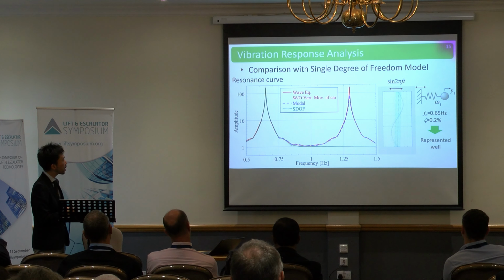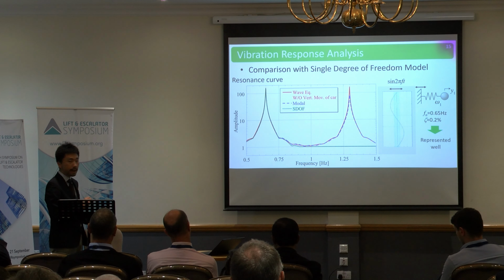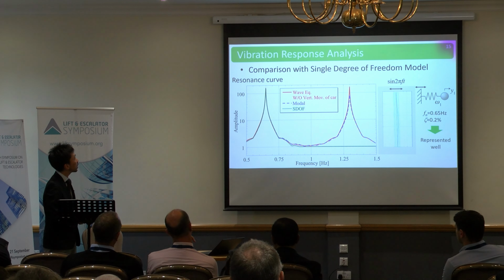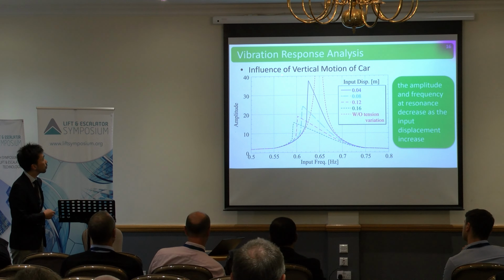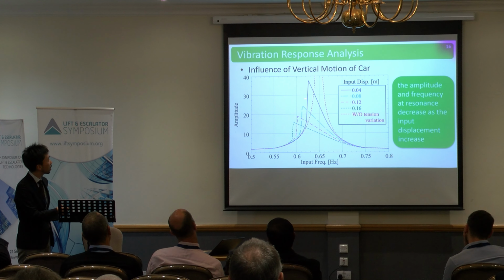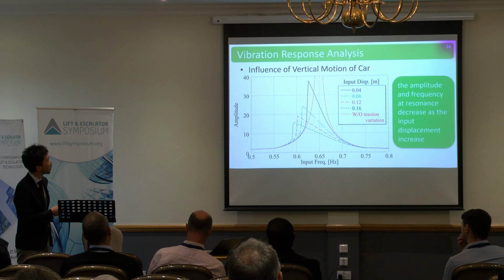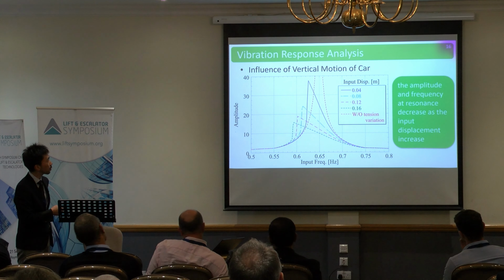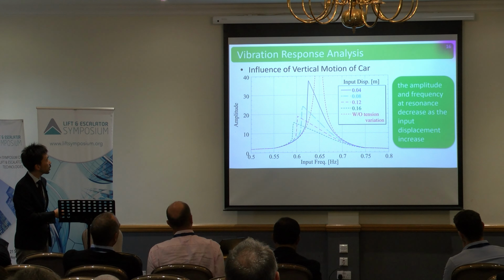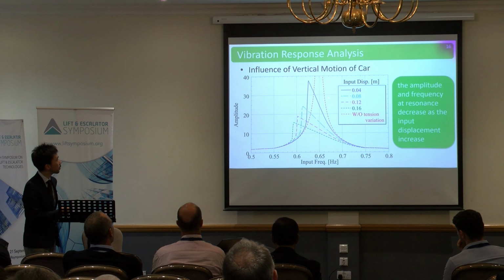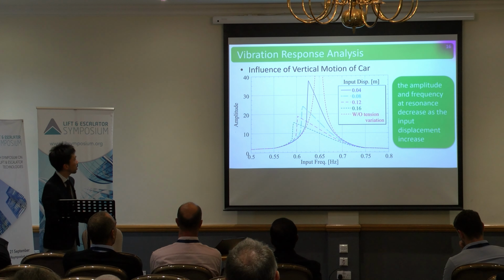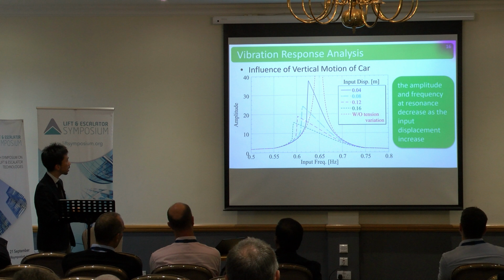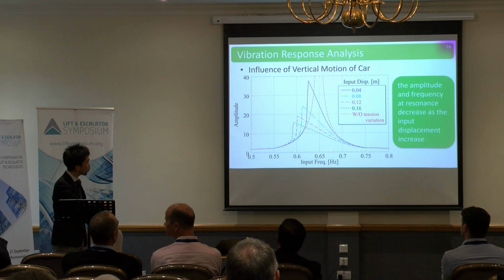So maybe we can use the single degree of freedom model and modal model for rough analysis of the vibration. However, if we consider the influence of vertical motion of the car, the amplitude and the frequency at resonance condition decreased as the input displacement increased. The difference of the lines indicates the difference of input displacement. As you can see, if the input displacement is large, the amplitude is reduced.